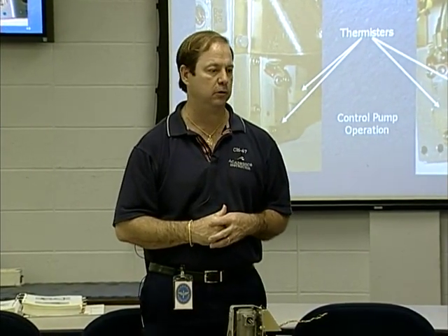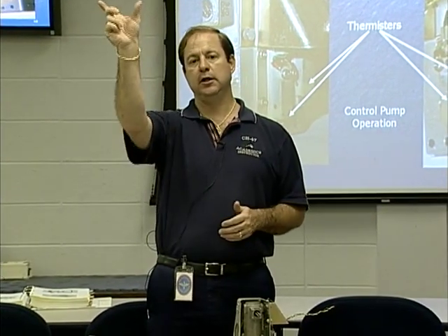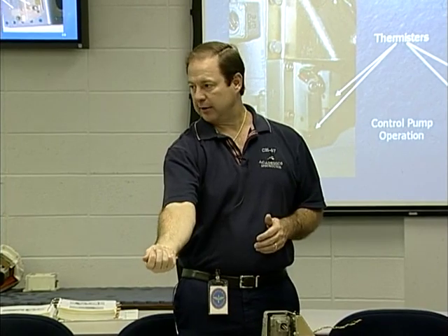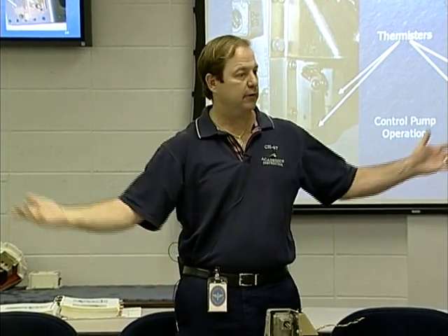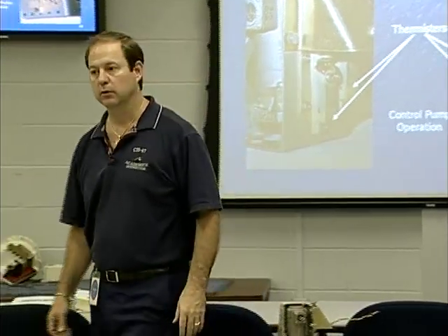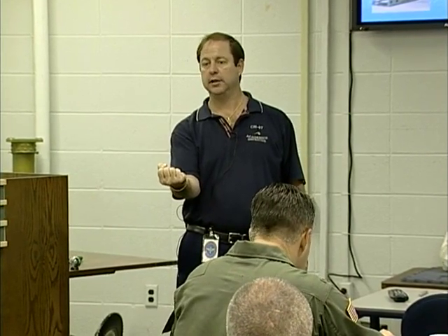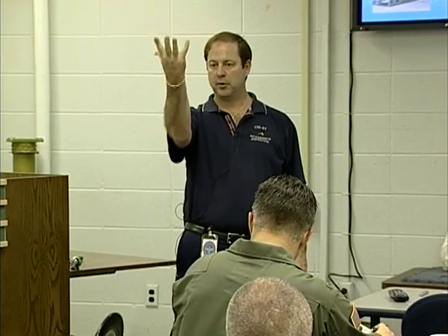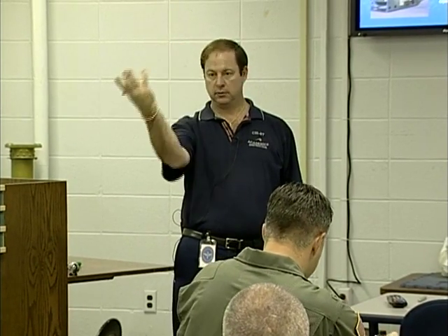Nope, no requirement to. Other than seeing the low pressure lights come on and verifying that those tanks are empty, that's all we do. Why? Because the pumps themselves have already been turned off via that thermistor system. Why did they become warm? Because there's no longer fuel in that tank, and now they're allowed to heat up. As long as both those switches are covered and the fuel's keeping them cool, they won't heat up.